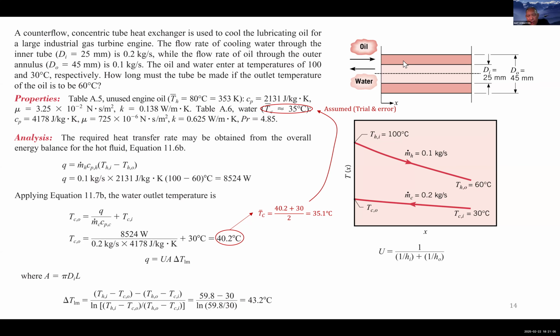First of which, convection resistance on the outside, the thermal resistance of the pipe, and the thermal resistance of the convection inside. So you need those 3 thermal resistances to be combined as the UA. Let me find my pen first. I'll write it down for you.